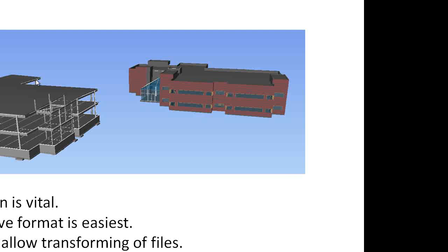I usually prefer to relocate the file back at the original source due to the minimal snapping tools available inside of Navisworks. And with the popularity of the building design suites, you now have that capability to do that easier than you have in the past.